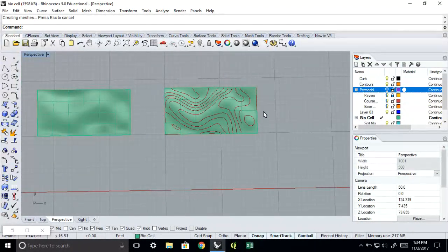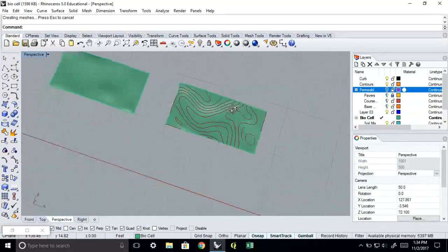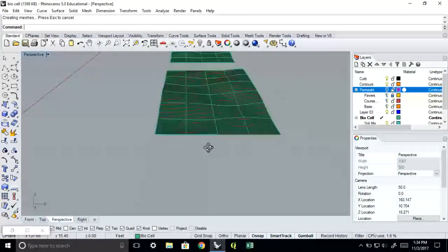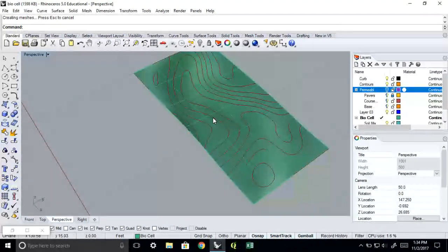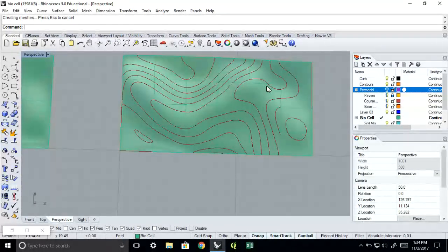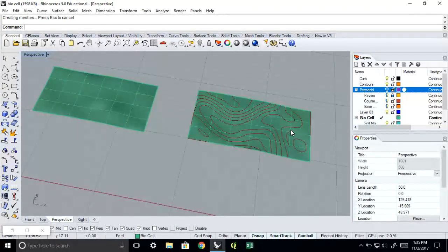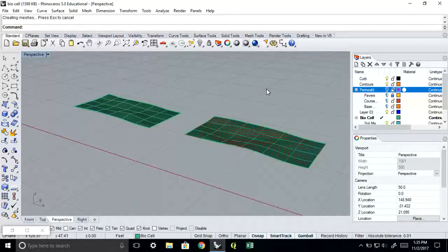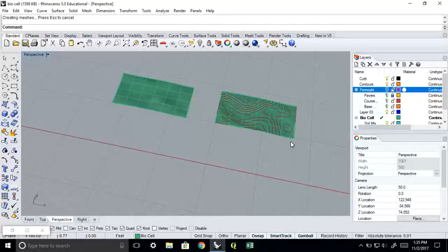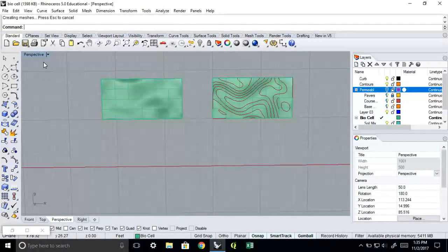All right, pretty cool. So you can start, like I said, by just taking that surface and adding some control points to it and start lifting them up, you can easily start to create this meandering quality to it where you can see how the water is going to start to follow these swales from your inlet to your outlet. So there's our surface. Now we have to actually start to create those conditions around it.